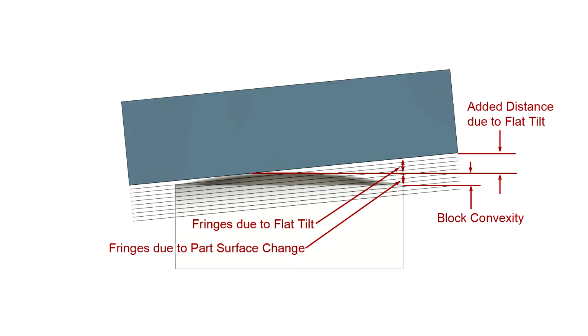At the right, the plane intersections now combine the vertical height of the surface plus the rise of the optical flat due to the tilt. The fringe lines reflect the distance from the flat to the surface, not the height of the surface alone. Forgive the repetition, but this is very important. Fringe lines don't normally represent lines of constant surface height. They are lines of constant spacing between the optical flat and the surface, and for any case where the flat tilts, the flat-to-surface spacing is not the same as the surface contour height alone. It's related, but not the same.